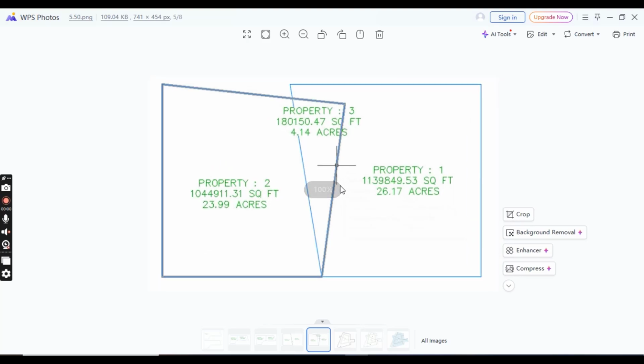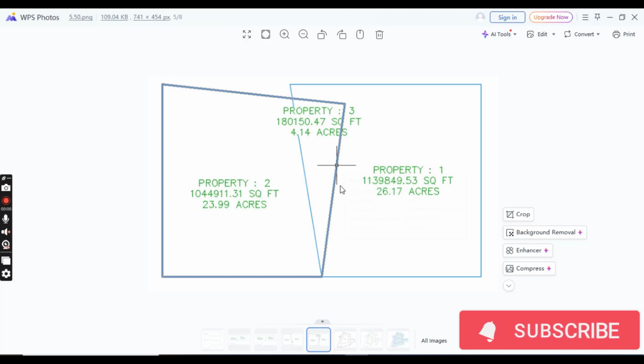So it is best practice to get data from LandXML to create closed boundary parcels. Parcels imported from LandXML will automatically clean up duplicate lines to prevent some of the pitfalls mentioned in this section.